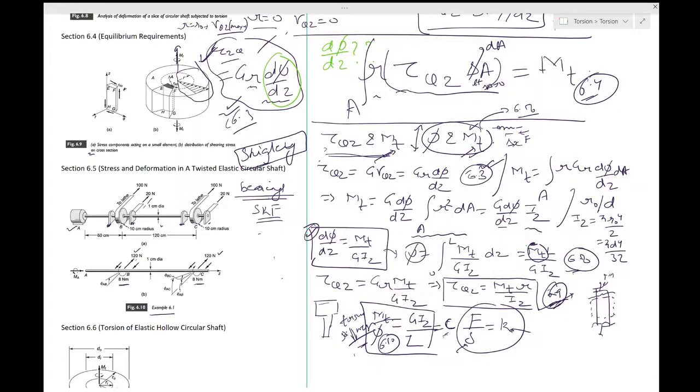It makes this rotation so smooth that practically the friction is negligible, and because the friction is negligible, you should not have a shear force over there, and that is why we can assume that there is no shear force or bending moment transmitted beyond the bearings. So there would not be any shear force or bending moment in this region.